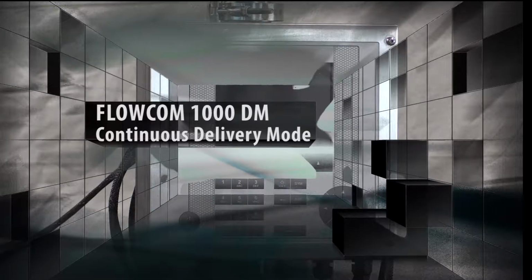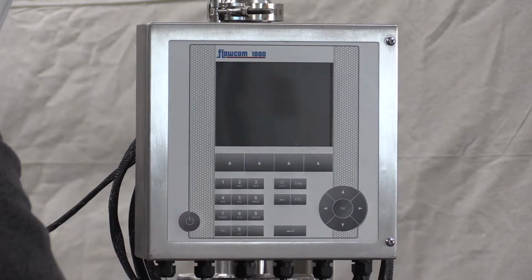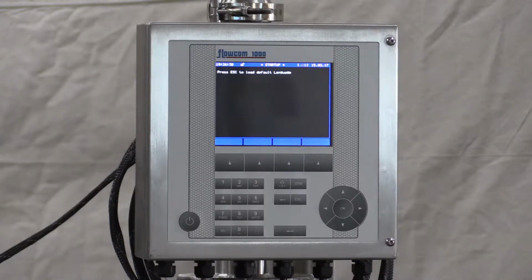This is a demonstration of a delivery utilizing the continuous metering mode. Pressing the on button in the lower left corner turns the FlowComm on. During power up, the FlowComm checks for errors and warnings. Per weights and measures requirements, the total displayed at boot up is the meter's total when the power is interrupted.